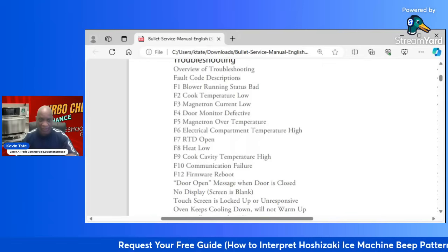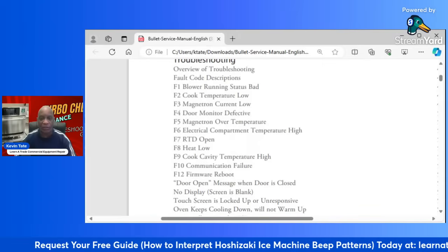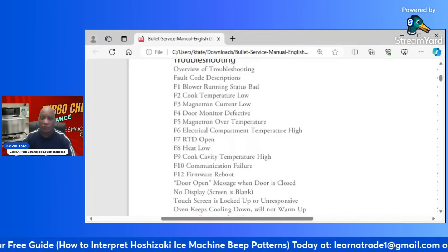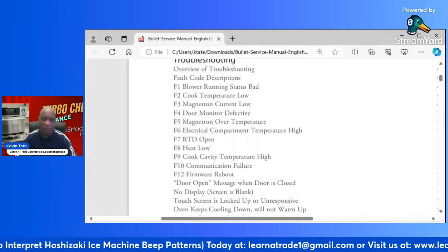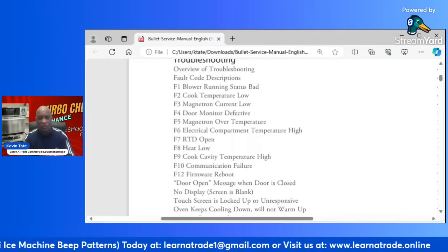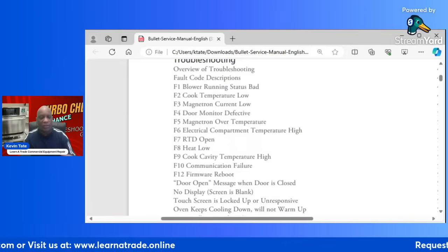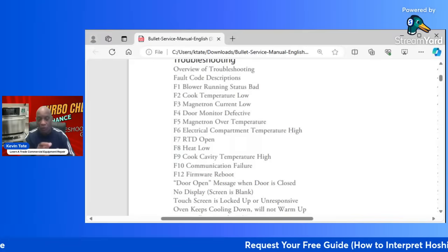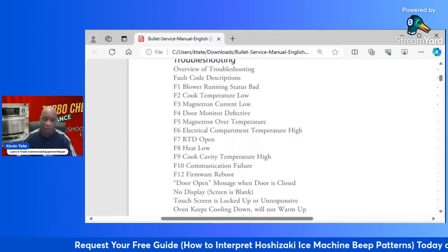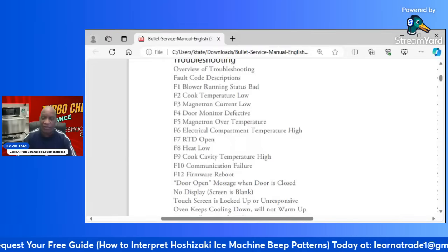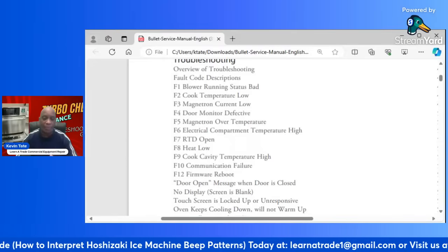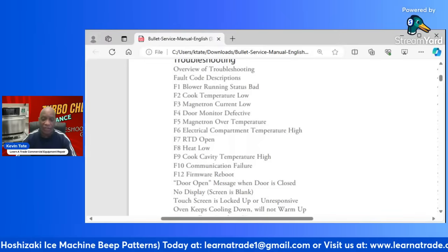find the K2 relay and take a look at it, because if that K2 relay has any damage, you'll be able to see it. It's like a clear plastic covering, and you can see into it. You can see the contacts. It'll look black, it'll look smoky inside, or the contacts themselves will be discolored. If they look discolored or any kind of damage, the best thing to do is go ahead and change that.